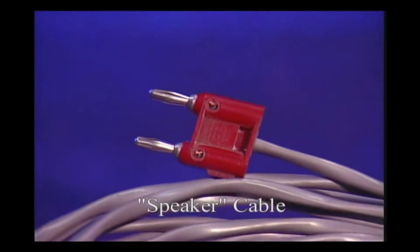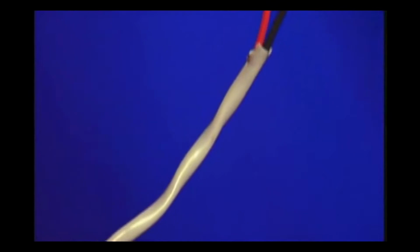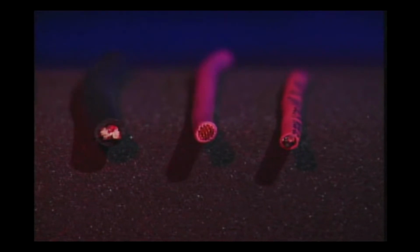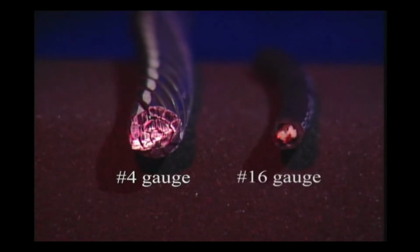Our final cable type is speaker-level wiring. This is the only cable type where shielding is not necessary or helpful. Normally we use simple 2-conductor cables. The diameter of speaker wire is given a numeric gauge number. The smaller the wire, the higher the gauge number. For example, a number 4 gauge wire is larger in diameter than a number 16 gauge wire.